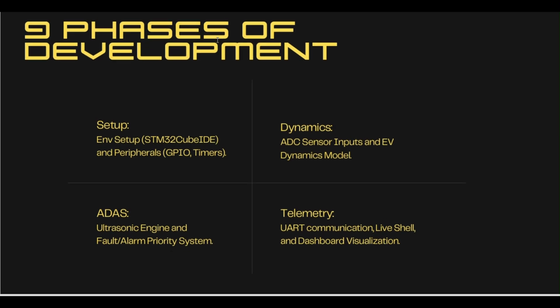Building an engineering project like this requires step by step planning. Our development roadmap is broken down into four main areas. We started with the setup domain where we configured our coding software, STM32CubeIDE, and turned on the microcontroller's internal clocks and pins. Next was the dynamic domain.